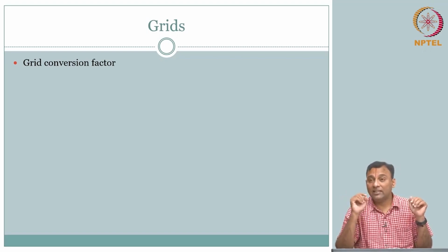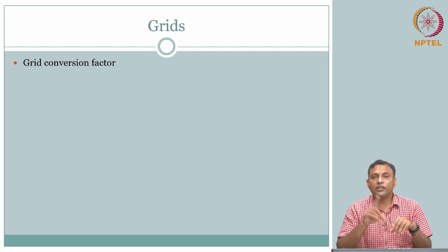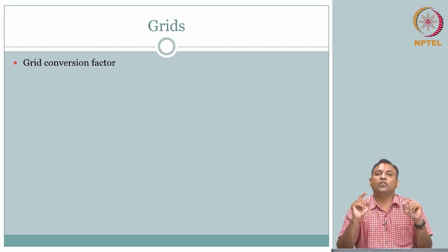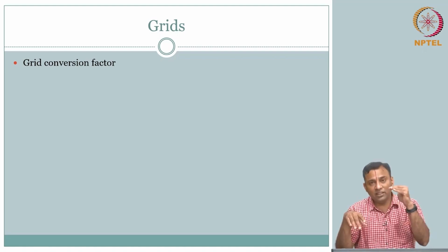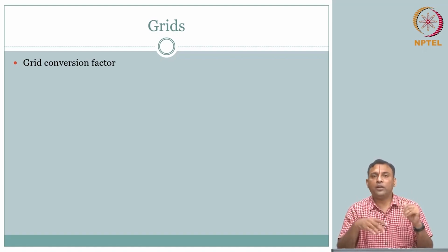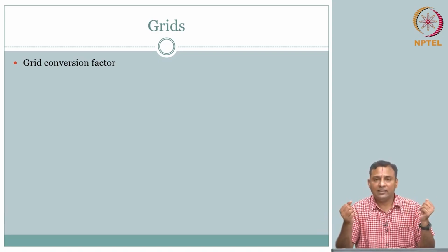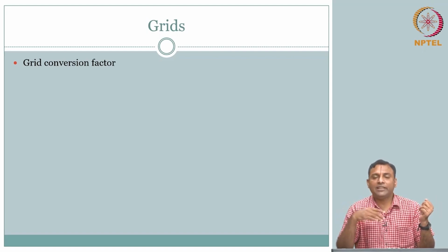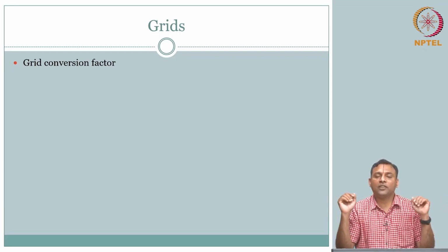So, in some sense I have reduced my noise, but I have also reduced my signal. What is of interest? Increasing signal to noise ratio. One way of doing that is reducing the noise for the same signal. But if signal is also reducing, is it prudent? Clearly not. So, how can we increase the signal for the given reduction in Compton scattering, or the noise? The only way is to increase the number of photons.